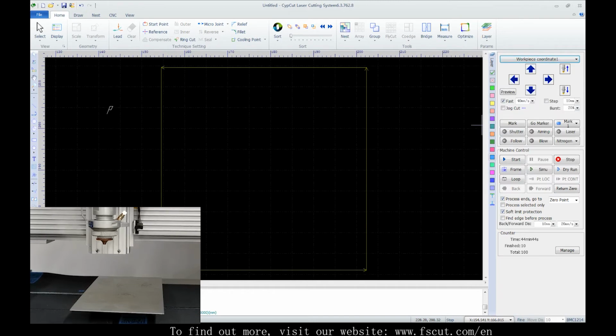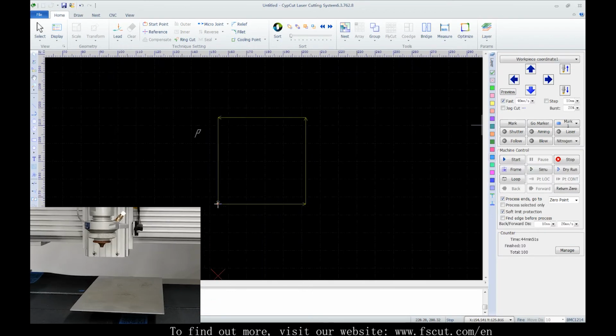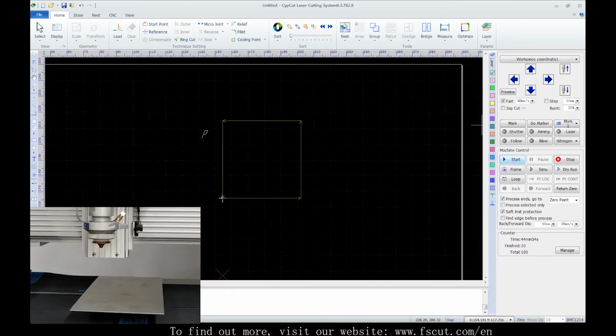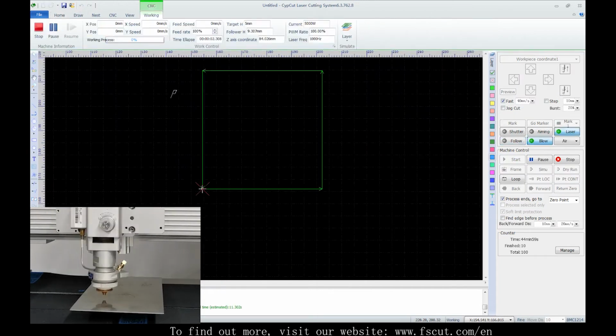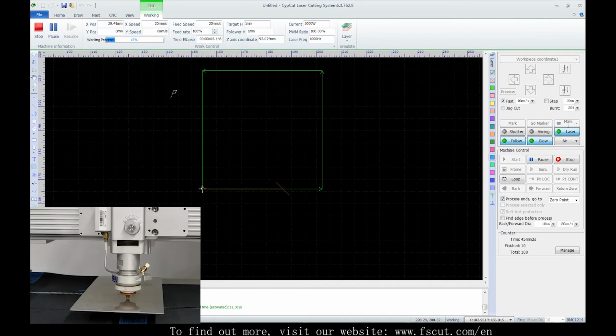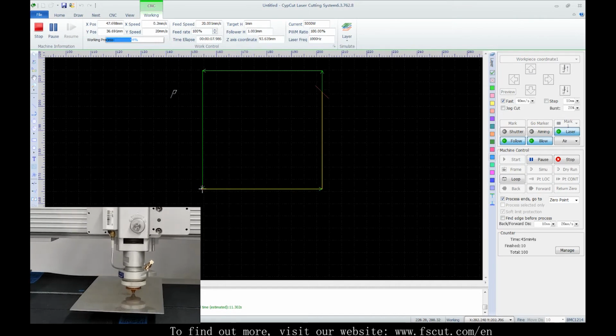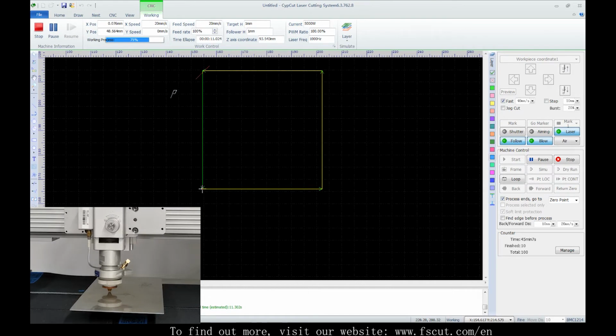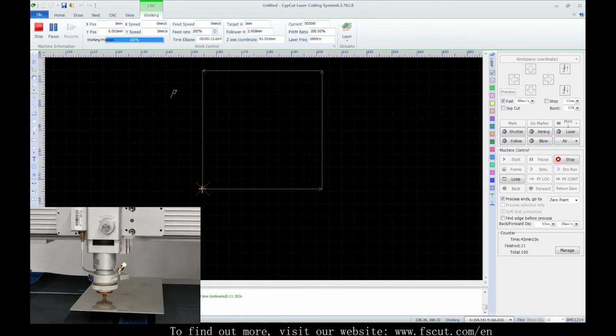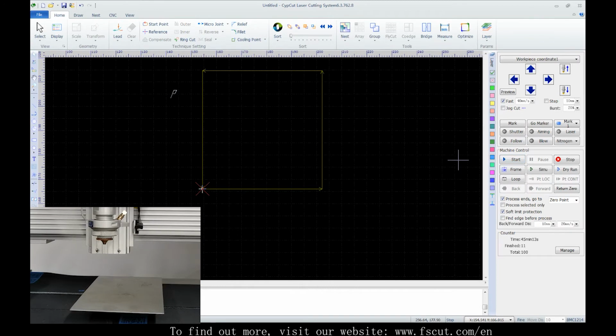During the process, if the cutting head was moved to another position, so long as it gets an instruction to start, it will return to the graphic next to the defined 0-point, and then start cutting. This coordinate is used in mass production scenarios where large quantities of plates of the same size are placed in the same position on the machine bed, which also requires a 0-point of fixed position.